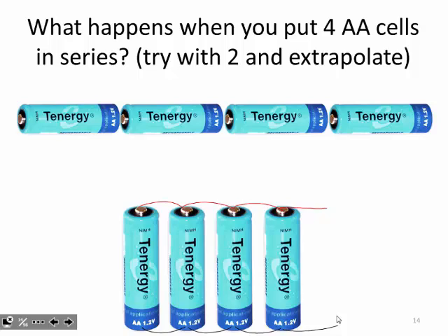But if you're just going back and forth a little bit, your screen is what's really drawing your power. Your screen, number one, and then your microprocessor, the type of microprocessor. Then there are other things constantly bleeding your energy: if you have your Bluetooth on, your Wi-Fi on. Your phone's always roaming, always looking for a signal. There are 3 communication devices on here, and your GPS, 4 things on in the background. You could turn all those things off, but then it's a computer, not a phone.